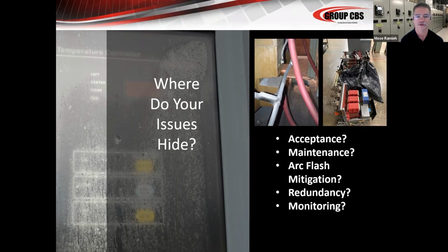There are things we can lubricate in a maintenance situation in the field, but there's a lot of things like bearings and other rollers that are not easily lubricated. So once again, the big warning is if you or your maintenance personnel are using any kind of spray, know that you're putting a Band-Aid on a problem, and you probably should take that breaker out of service, get it remanufactured with new bearings, new grease, have it torn down and put back together by a qualified, and I would always recommend a Pearl accredited company.